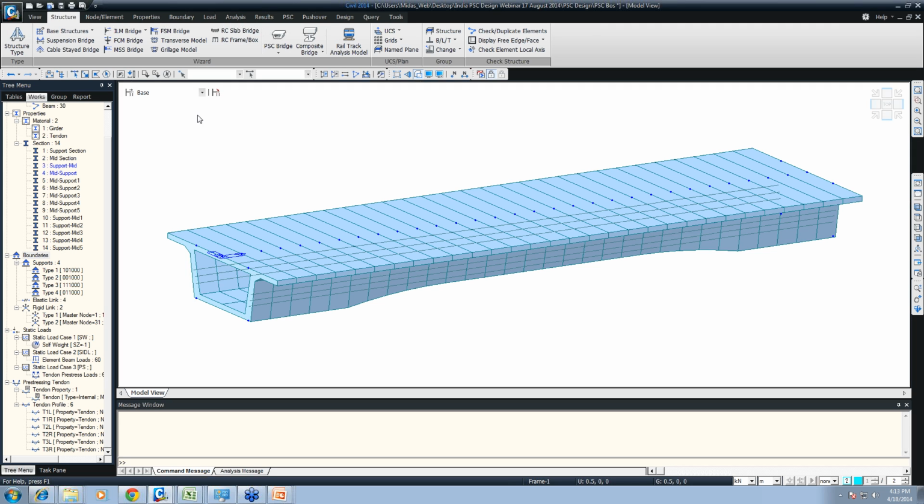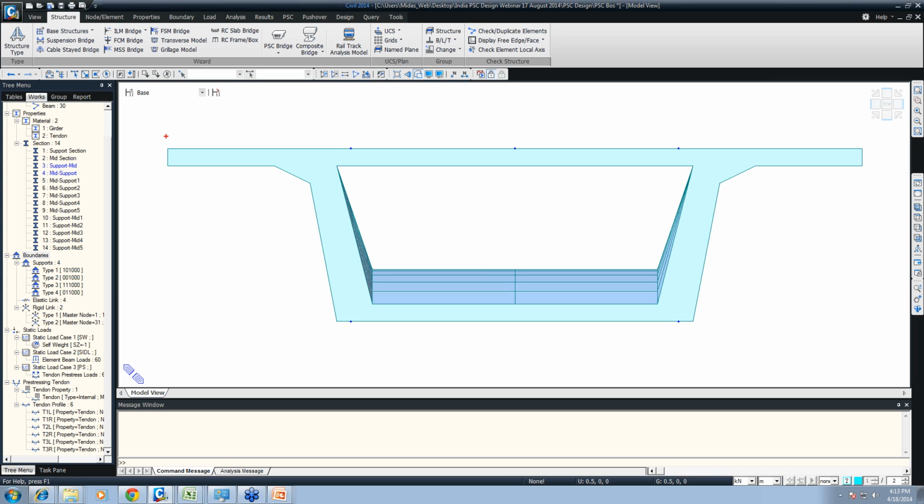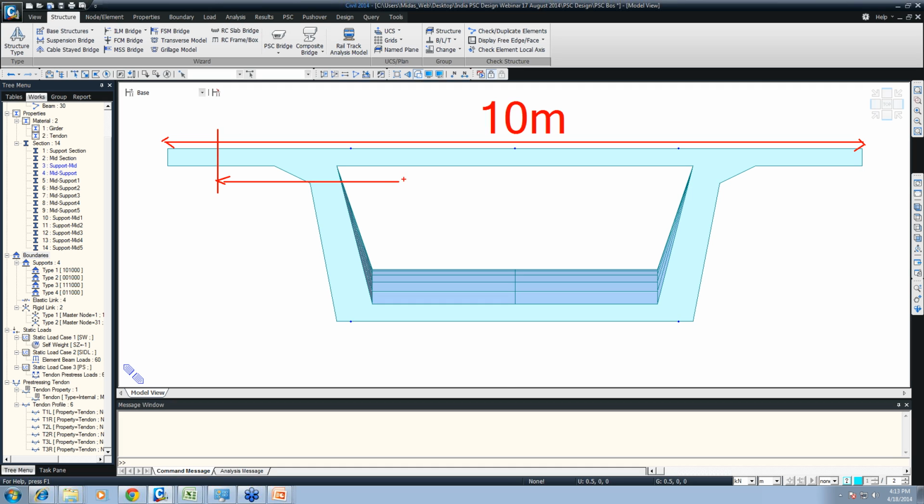Next thing is to define the moving load. Usually, because this brace is around how many meters? It is around 10 meters, more or less. So if we define suppose 1.25 something at the ends, so remaining length for the carriageway will be around 7.5 meters.